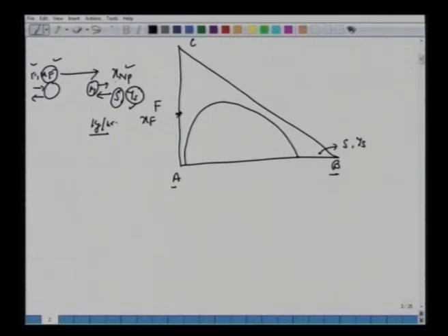So now if we connect F and S, then we can have somewhere here the mixing coordinate M. So let's say that we have some coordinate M. Okay, so this represents the combination or mixing of F and S. And now, since we know the raffinate coordinate here, we can connect this to obtain this E1. So this would be E1.